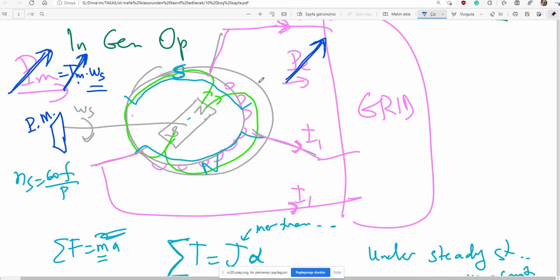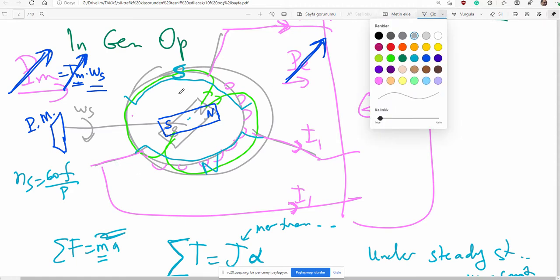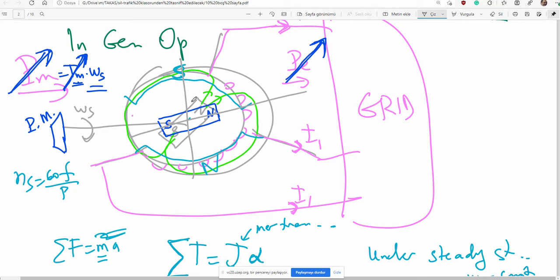Okay, but ladies and gentlemen, when you apply more torque, the rotor leads a little bit. Rotor will be like this. The angle between stator and rotor magnetic field, let me say delta load angle, will increase, but there is a limit.